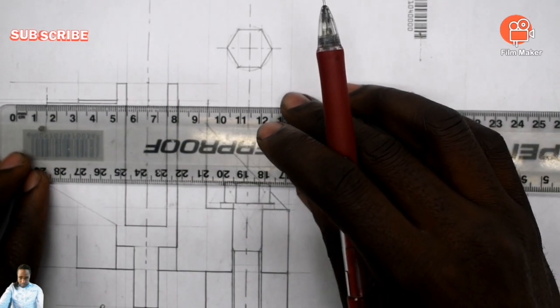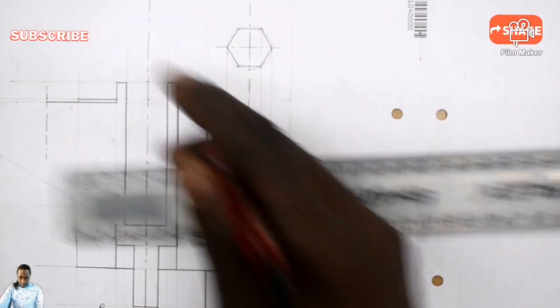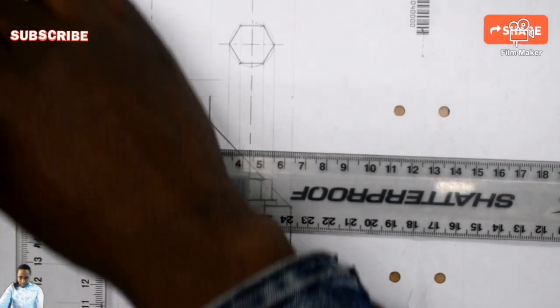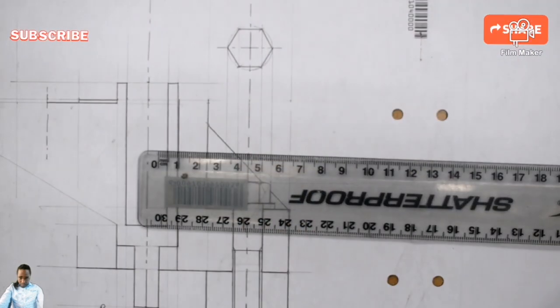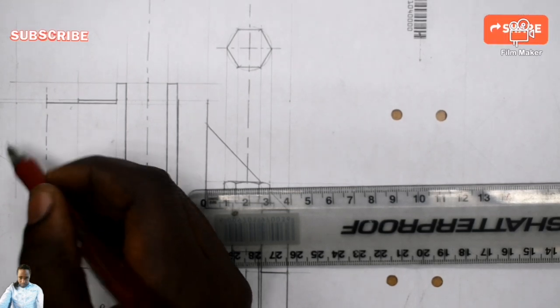So there is my 15 millimeter. So I mark here. After I've gotten that mark, I construct a vertical faint line. You understand? So now from here, I must get a radius 10 millimeter.